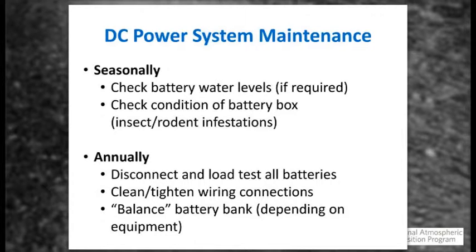Annually, you'll want to load test all your batteries. We've got some pictures just showing what this means. Many places like AutoZone will do it for free, but we'd recommend, if you don't have a load tester on site, to get one, or take the batteries to a local place that would test them. Clean and tighten your wiring connections. Look for corrosion, and make sure they're always clean and tight. And then depending on your equipment, you can balance the battery bank, and that has to do with rotating the batteries. It's a little bit beyond the scope of this presentation, but we can provide further guidance or resources that talk about that.